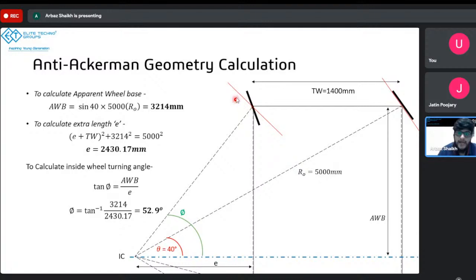And if you have the slip angle for each of the wheels, all four wheels, and if you have the angle over here with theta, phi, you can calculate by how much you want to turn your wheel actually, right? Once you have that, you can easily go on to your calculation for your steering, the rack travel, pinion, similar to what we did in the Ackerman geometry calculation. And this is why I wanted to take you through the Ackerman geometry calculation first, so that this part is the only difference between that and this calculation, right?